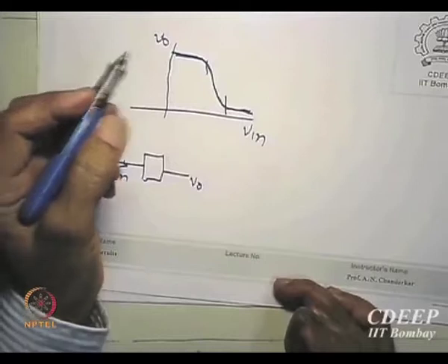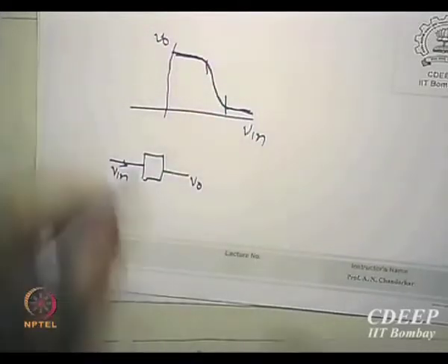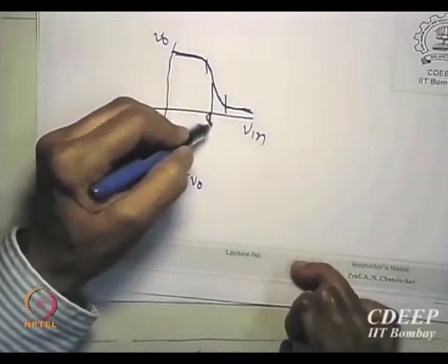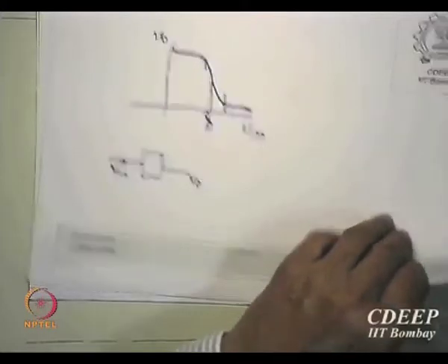Is that correct? So we cannot use an amplifier in regions where there is no gain, then why call it an amplifier? And therefore, we must operate within this range of DC values, and therefore the signal should not exceed either side. Let's say if I bias here, the signal which I put here should not cross these 2 points any day, because otherwise you will get into a gain 0 kind of stage or much lower gains at those points. And therefore the amplifier will not act like a good amplifier. Is that clear? So small signal is not that I don't want to do better, I can't do better, and therefore that's the limit which I will always try to follow. However, all said and done, this is fine.